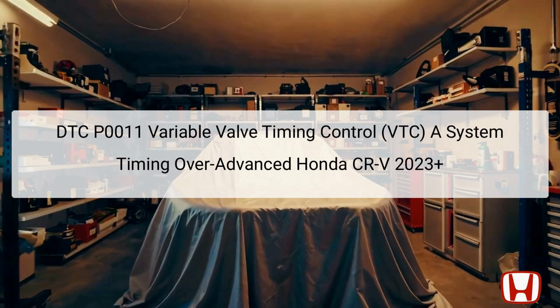The VTC system plays a crucial role in optimizing engine performance and efficiency by adjusting the timing of the intake camshaft based on engine conditions. If the VTC actuator or solenoid malfunctions, it can lead to performance issues or increased emissions.